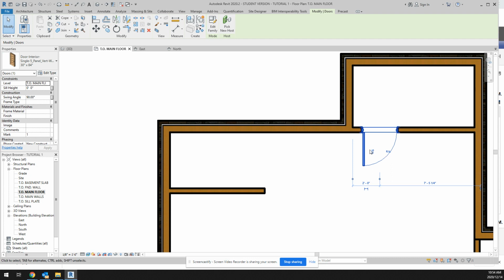So in this particular case, when you talk about the hand of a door, it's referenced from looking on the outside of the door. So I'm out here somewhere looking at the door. This would be a left-hand door, okay, with an outswing. I've mentioned before, especially when you go into rooms and bedrooms, it makes most sense, except in commercial applications like this type of building where for safety reasons and exits, you need to have it swinging out if it's an exit door. If you want to change the swing direction, I just hit the flip button and now I've got it swinging in, right? That is how I want this door to swing into this particular space.